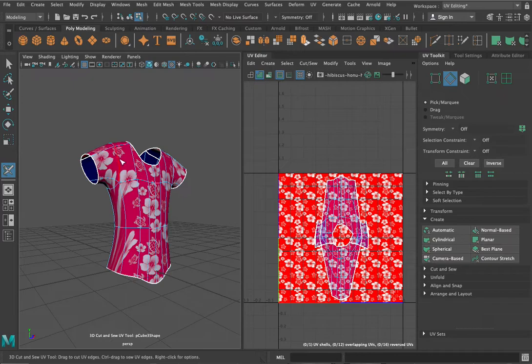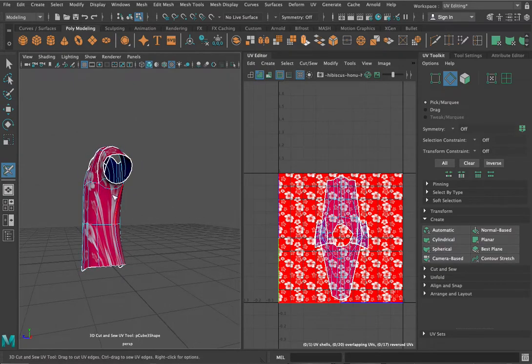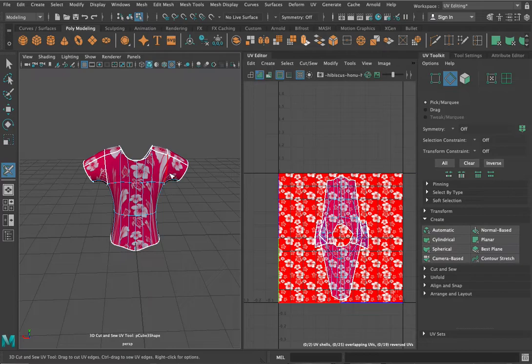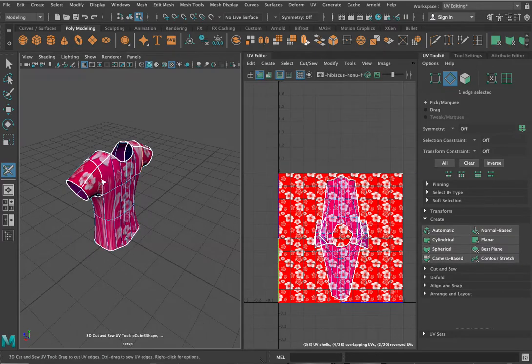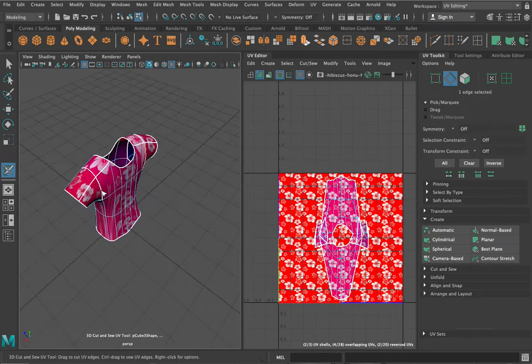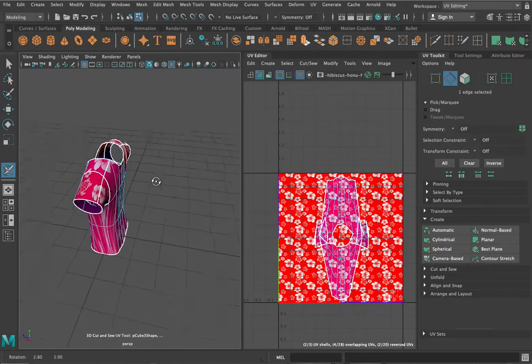And maybe what I could do here is put a cut on the arm. So I'm just double clicking because that quickly adds a kind of circle here. So now I've put a seam right around here. It means that those whole arm bits are going to be cut off. And because there's a cut through here on them, it means that this will be able to be flattened out. So you can imagine that this is like a cylinder that will come off. And then we've got to cut down the side of the cylinder so we can lay the cylinder flat.